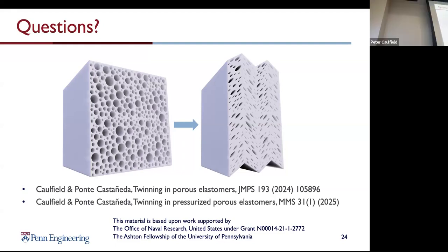So you can do two different experiments. One would be uniaxial compaction, where you fix the deformation in this direction to not deform at all. Another one would be uniaxial stress, where you allow this to be a free surface, so zero stress, but you'd expect that as you compress it, it would expand this way.